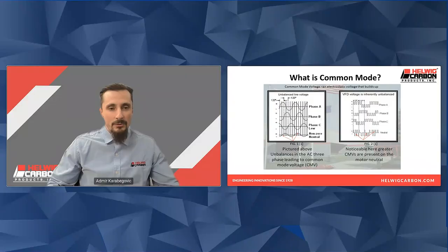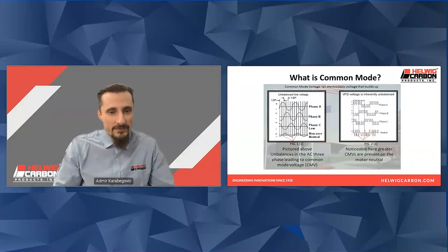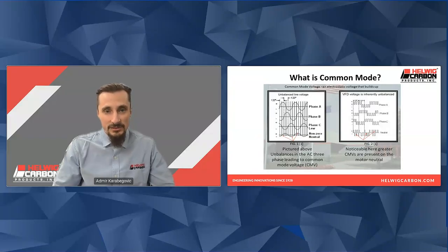So what is common mode? On the left here at the very bottom, we show an imbalance in the AC waveform from a VFD, which creates this common mode voltage. This common mode voltage then gets parasitically coupled to the motor shaft and then discharges through the bearing to ground. Similarly, on PWM systems with DC motors on the right, a similar thing happens where we have an imbalance in the waveform as it relates to the motor neutral. And this again creates this common mode voltage, which gets parasitically coupled to the shaft and then tries to find the path to ground, which will be through the motor bearings.